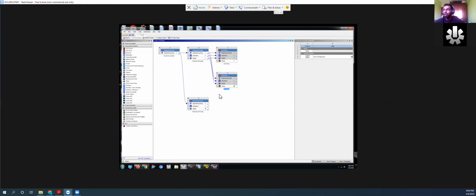And you'll see that all the lines will connect to the appropriate things. So remember what I said about ANSYS being pretty much a bunch of toolboxes with a flow going on. All of the data that you created in the mechanical model will go into ACP Pre. So in this case, you can have 2 different ACP Pre for the same mechanical model. One reason why you want to do this is because you're testing multiple different layups, and it's just easier to have different setups going forward so that you can analyze them differently and see which one works best.